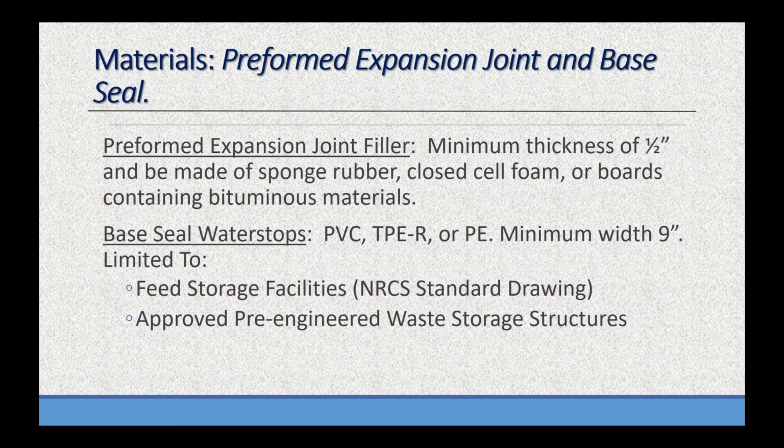This year, we get to use base seal water stop, PVC, TPE, or PE. Minimum width is 9 inches, but they are limited to feed storage facilities, NRCS standard drawings only, and approved pre-engineered waste storage structures. So if it's a pre-engineered structure that we've had in the past, and that is in that package that NRCS approved, we can use that base seal. Otherwise, don't plan on using it on a standard waste storage facility that we're designing. It's really only used for the feed storage facilities with the NRCS drawings, that's a caveat, and approved pre-engineered waste storage structures.